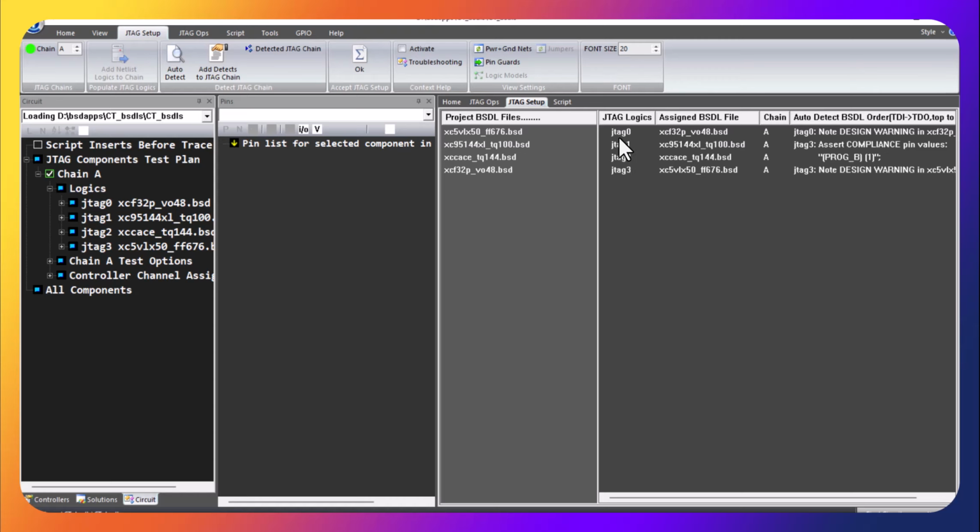And these are the default reference designators that are assigned, but since we probably know our board, we know what the reference designators should be, and we can simply edit in place, change these all, U2, U1.